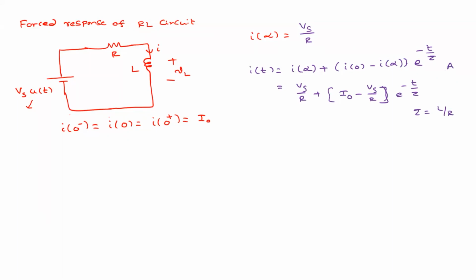So how to solve this one? Here the current is given, so now apply KVL. Vs equals R into I plus L into di by dt. Our objective is to separate the di terms and dt terms to one side. If you rewrite this, di by Vs minus Ri equals dt by L. Agree? Is this correct?